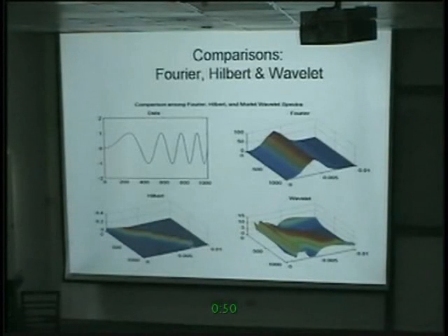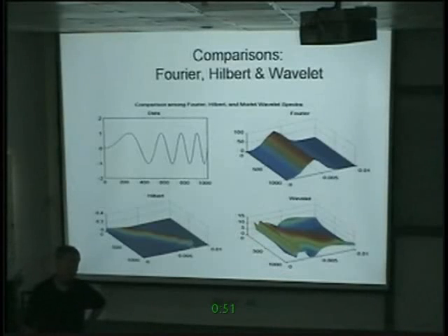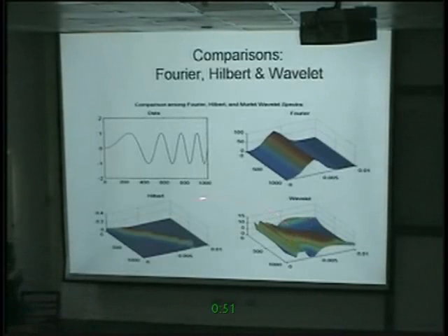Yes, you can use discrete, but discrete only has a few frequencies. You may find 4 or 5 frequencies. That does not give you a continuous line. So you have to use this overly redundant method to get a pattern. For wavelet, if you want to compress an image, the discrete wavelet is the wavelet of choice. But if you want to see the meaning and extract features, continuous wavelet is the choice. But as I said, continuous wavelet has all these problems. Now we move from continuous wavelet to Hilbert, and that's very clear.